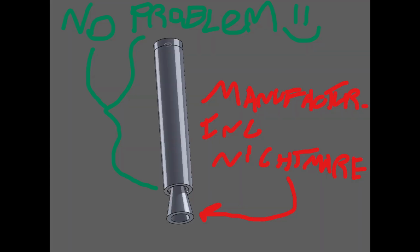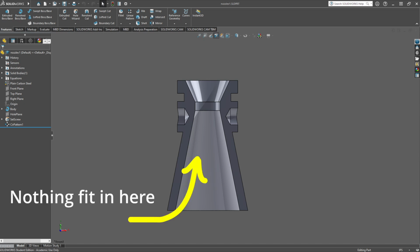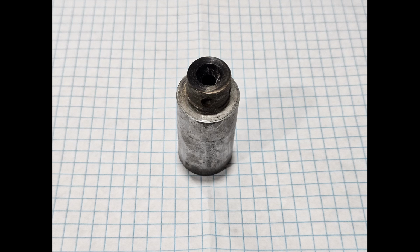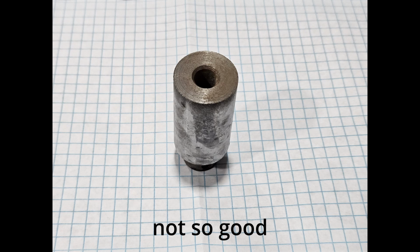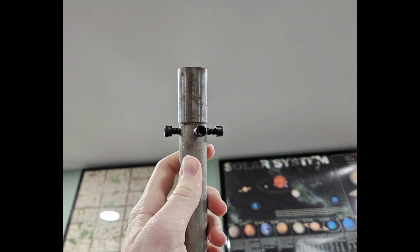So, it turns out that my nozzle is pretty difficult to manufacture. I attempted to lathe it out at my FRC shop, but there were no lathe tools that were small enough to fit inside the engine bell to create the diverging section. So what I ended up with was a nozzle with the correct throat diameter and converging section, but a diverging section that was much smaller than it was designed to be. Even so, I decided I might as well test it out, as I had already put an entire afternoon into building it.